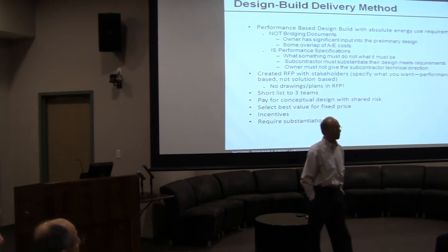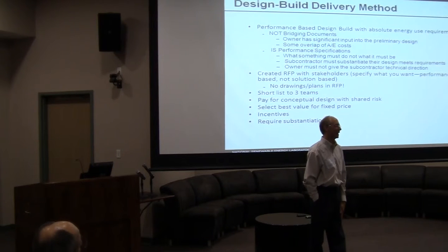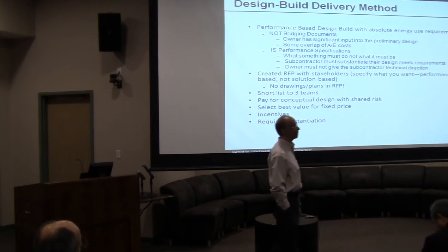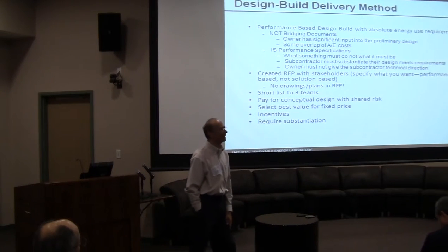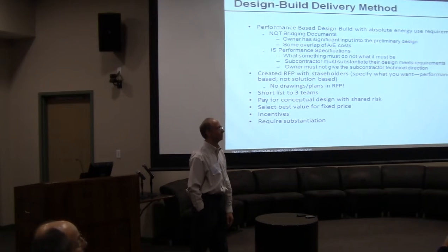We gave them a plug load profile. Plug load, light load, whatever. Well, the lighting load was based on occupancy hours that we provided, but then obviously they were trying to get daylighting into the space to get the lights down. But temperature schedules, temperatures, all that stuff was given. It had to meet ASHRAE comfort standards. All of that was in the RFP. We don't get that for most of our owners, by the way.